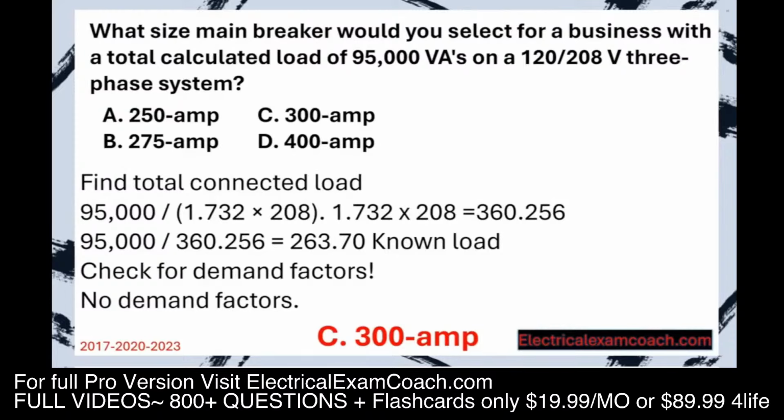The beauty of three-phase is the numbers come down. So this one's on a 300 amp service, which means we can put it on smaller wire, which might mean we can put it in smaller pipe, which might end up having a smaller overall cost.